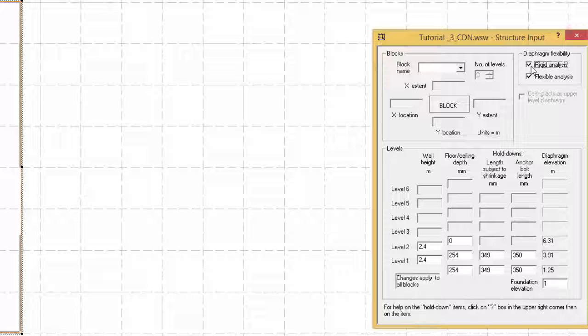However, if a rigid analysis were to yield 5% on one line and 95% to another, while the flexible analysis is found to be 50-50, the engineer should probably design for the larger of the two loads for the individual walls. Therefore, engineering judgment shall be applied when deciding to design for only one diaphragm case.